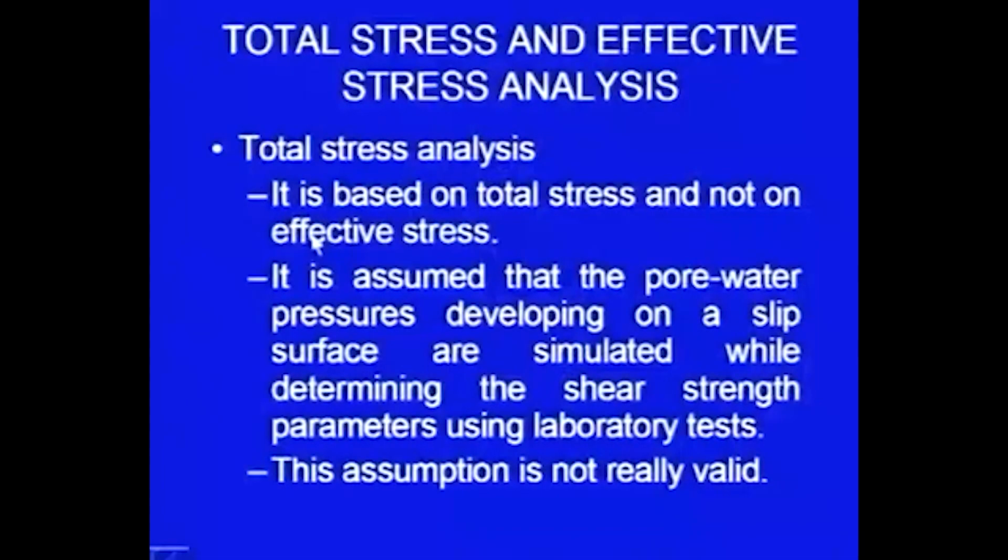Now, some discussion about the total stress and effective stress analysis. These are the terms which I have been using. Total stress analysis is based on total stress and not on effective stress. We have already discussed what is total stress. Effective stress means after subtracting the pore water pressure. So, it is based on total stresses. We take into account the total stresses.